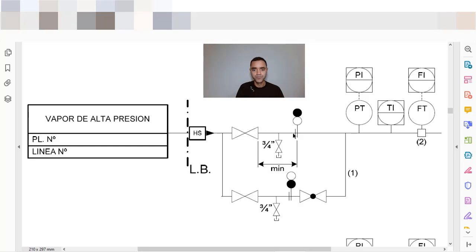is isolated. And in the main part, this one, you will let it open, because once it is pressurized, you will not open the figure 8 again, because to deal with this figure 8, you must untighten the bolt to rotate it, and you cannot do that in a pressurized pipeline. Here, to rotate the figure 8, you will close both manual valves and open the drain, so you will depressurize everything that you have here.